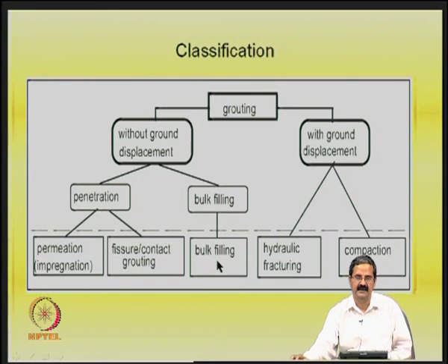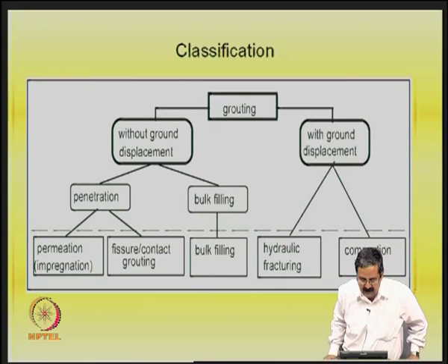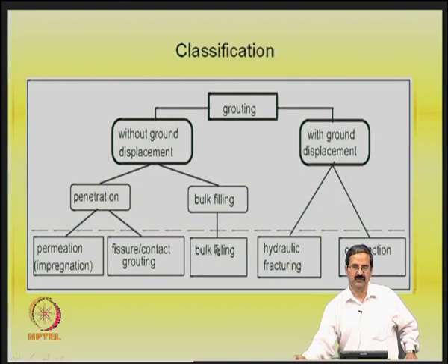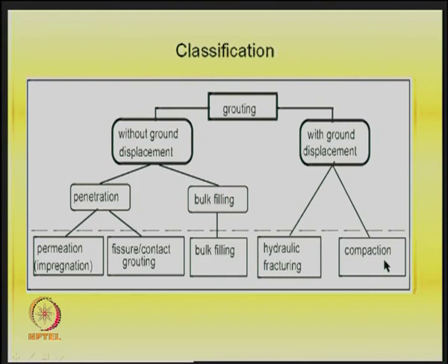You should know the exact volume. In fact, GPR and other techniques can be used to find out the cavities in soil areas. In slopes there could also be some problems, so one can use grouting to do this filling and see that it does not lead to any stability problems. With ground displacement, it leads to some sort of hydraulic fracturing, because you are pushing the material, and also compaction. So, it really densifies the material, that is one thing.